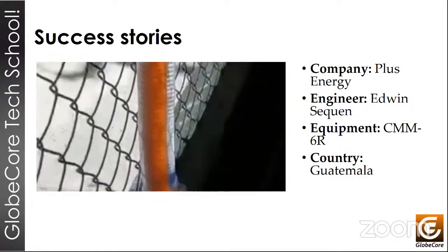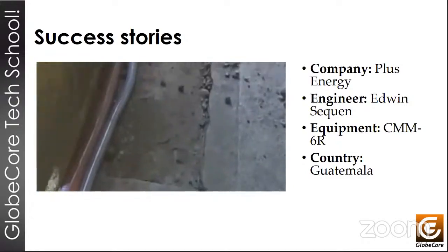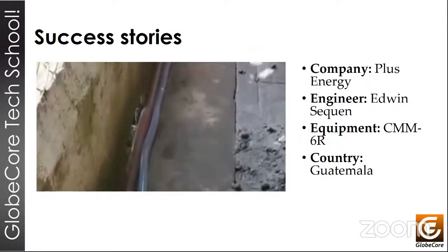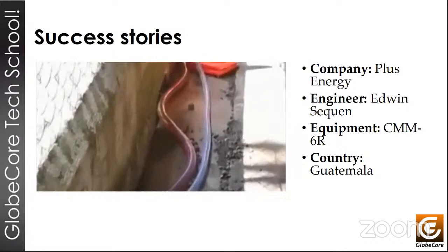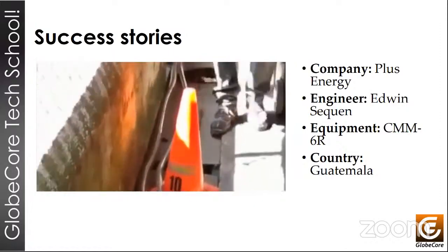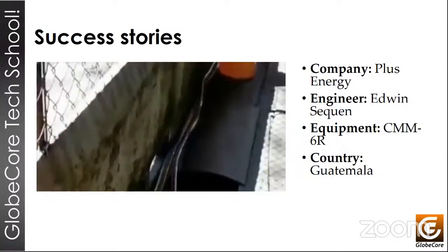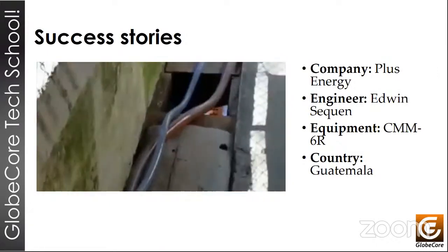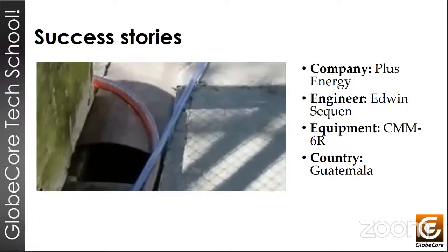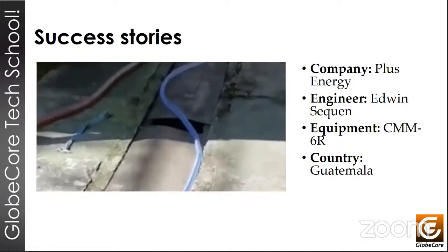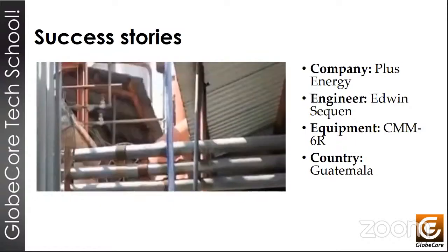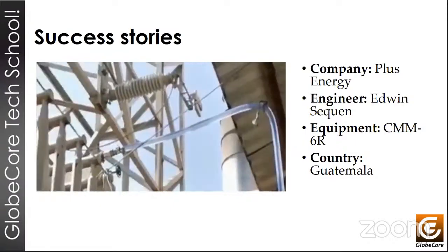This is the dirty oil that comes into the regeneration machine from the transformer, and the clear line on the right, the hose with the clear oil, is the oil after regeneration. And even through these semi-transparent hoses, you can already see the difference. And this is done on the transformer without turning it off, so you can see how the clear regenerated oil goes back into the transformer from the top.